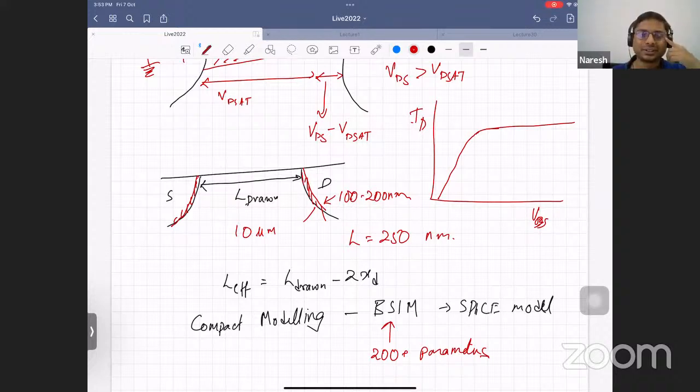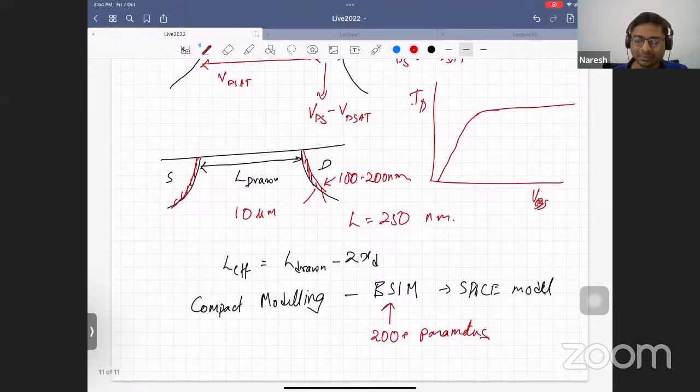Okay. So the issue is, Piyush, we can't even say that it only decreases, because you can have different types of defects, right? If you have a positively charged defect, in an NMOS it reduces VT, but in a PMOS, what happens? A positive charge defect will repel the holes from the inversion layer, so it actually increases the threshold voltage in a PMOS device. The other problem is these are not very easy to control. So we generally don't try to introduce defects or control the characteristics this way, because even with all these traps, carriers can trap in and trap out. Detrapping can also happen, so there can be unpredictable results.